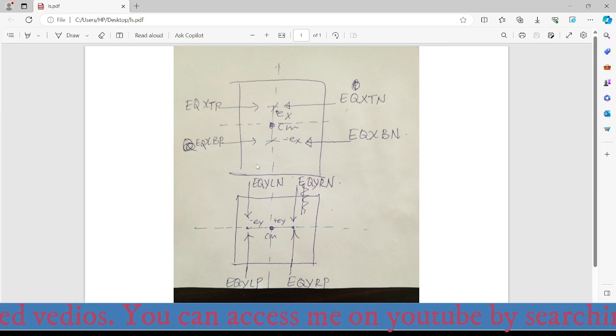So now let me show you some pointers that should be taken into account while combining the load. Actually, I have already told you that we need to avoid redundancy of the load combinations that will create a longer time of analysis for ETABS and the logic combination that will not be adding any values to the structural analysis and the design here.